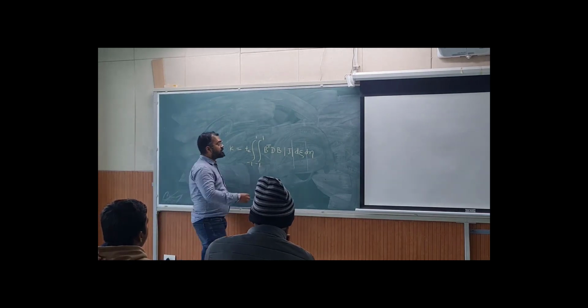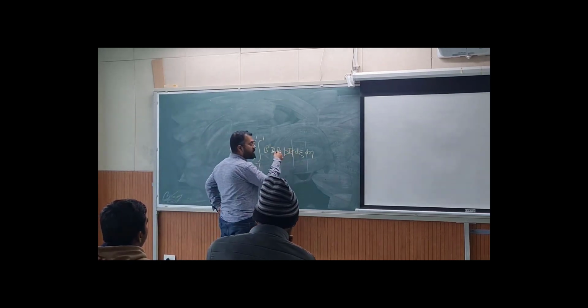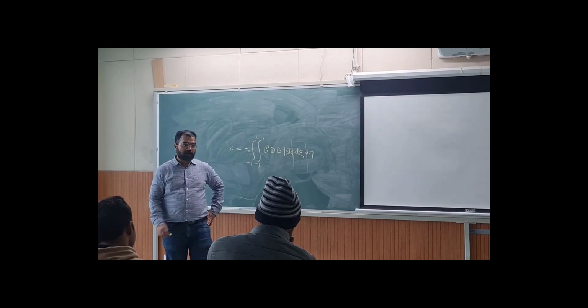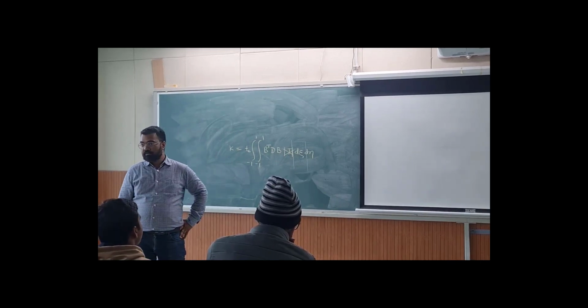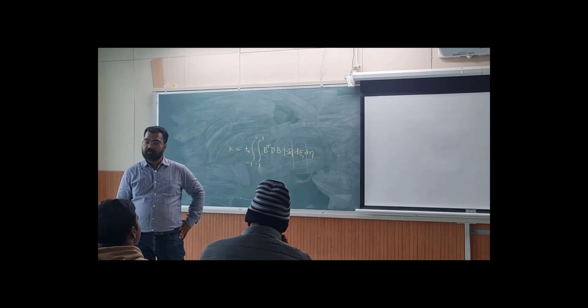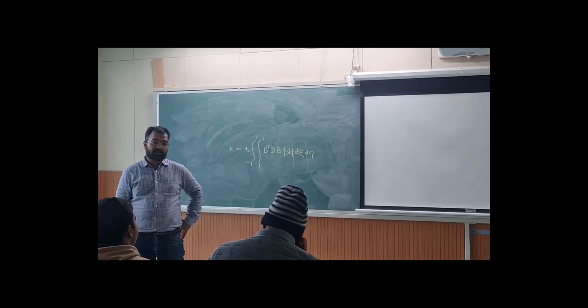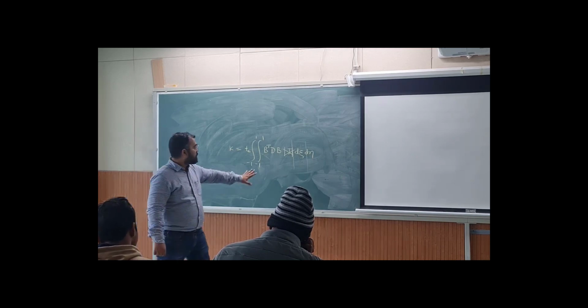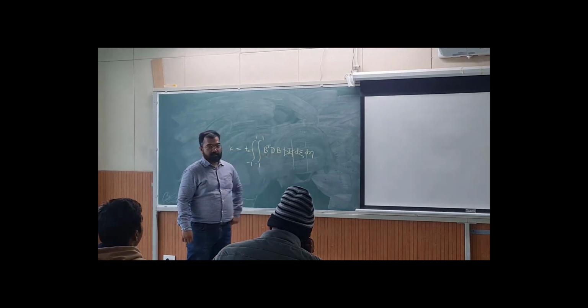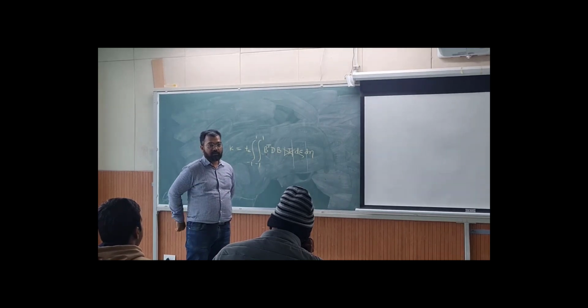So forget about this because that's the determinant, so that is going to give you a constant value. Just tell me the order of the matrix which you will have for a quadrilateral element. The number of rows and columns. Like which matrix? B or the total? B transpose DB. Okay. The whole thing.